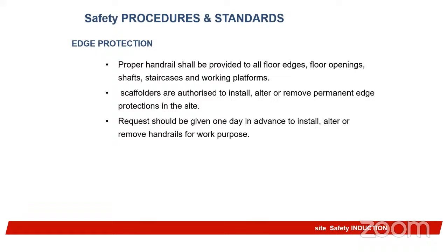The reason why you are having edge protection is also because of tools, like the tool board that we talked about the other time. In case a tool wants to fall down, it won't drop on someone who is walking under, at height, as the case may be. Scaffolders are authorized to install, alter, or remove permanent edge protection on the site.